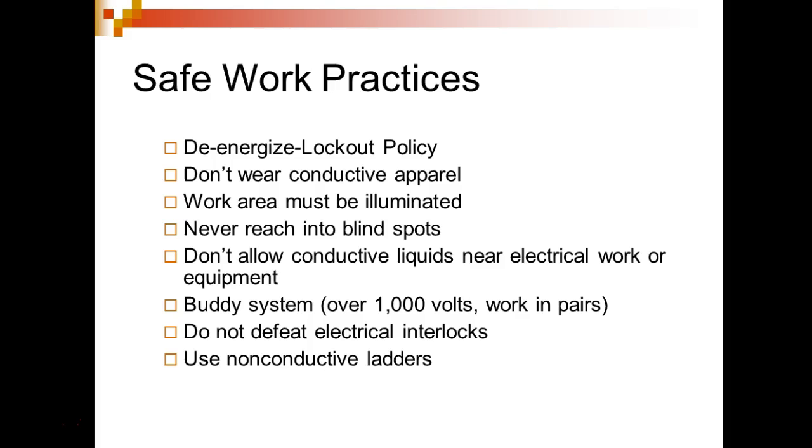They gave us a lock with one key only. If you ever encountered a lock that had two keys, you were to throw it away immediately. It was to be destroyed. You had the brass tag with your last name and your badge number. That's all that was required. It was the brass tag on the lock. Okay, so that would meet the tag out condition.